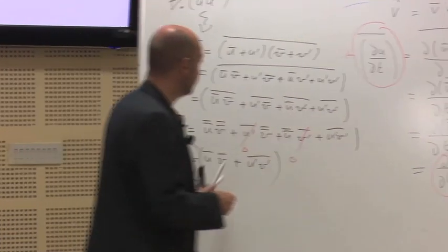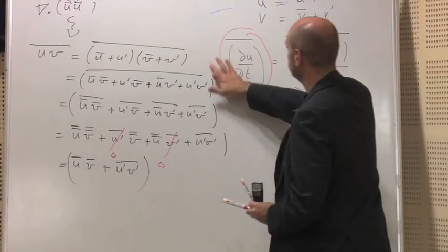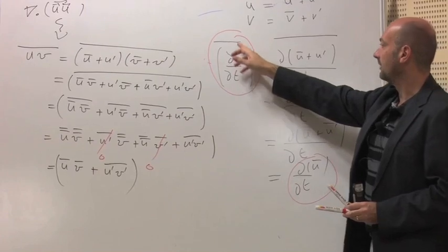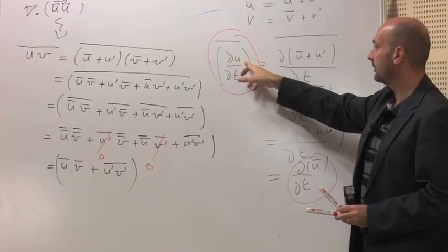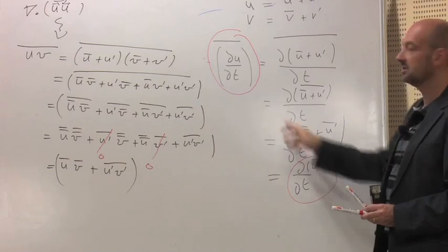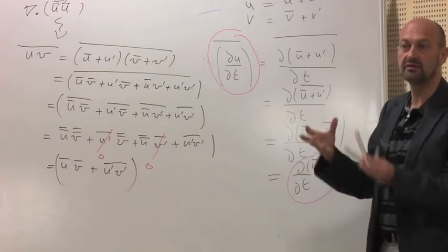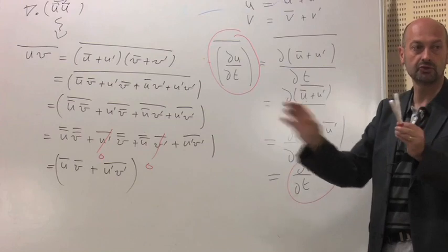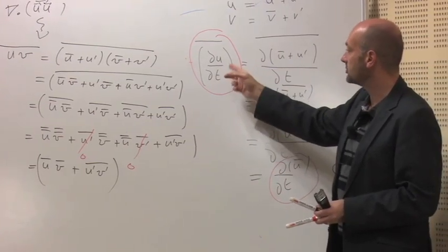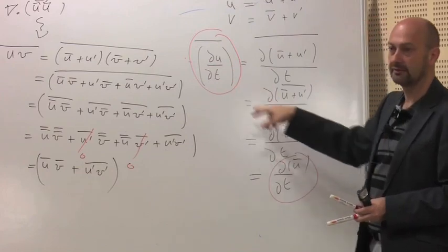So if we compare these two expressions, you see that for the temporal derivative, the average of the temporal derivative is actually the temporal derivative of the average. So you see that there is no modification in the equation. This is the same term. You just have to add a bar. So the Navier-Stokes equation for that term will not be modified.